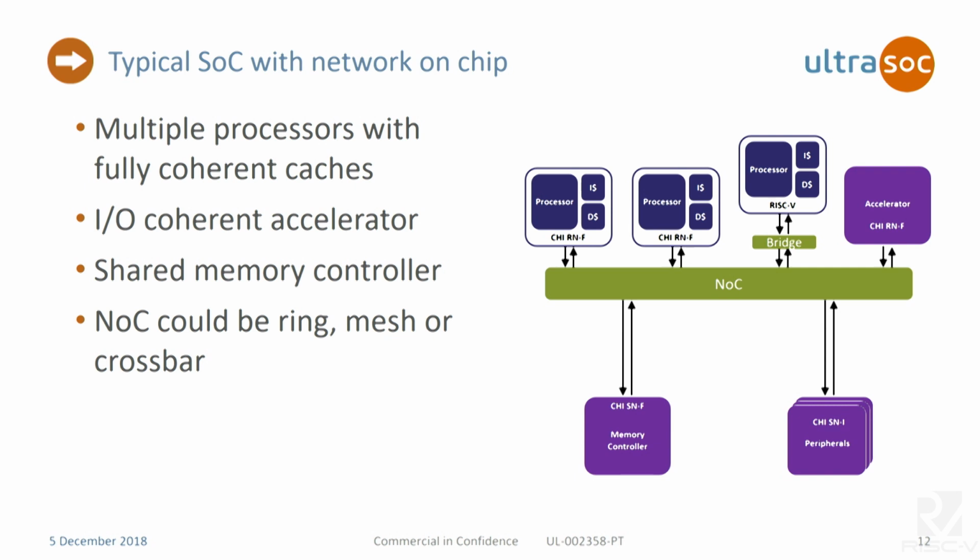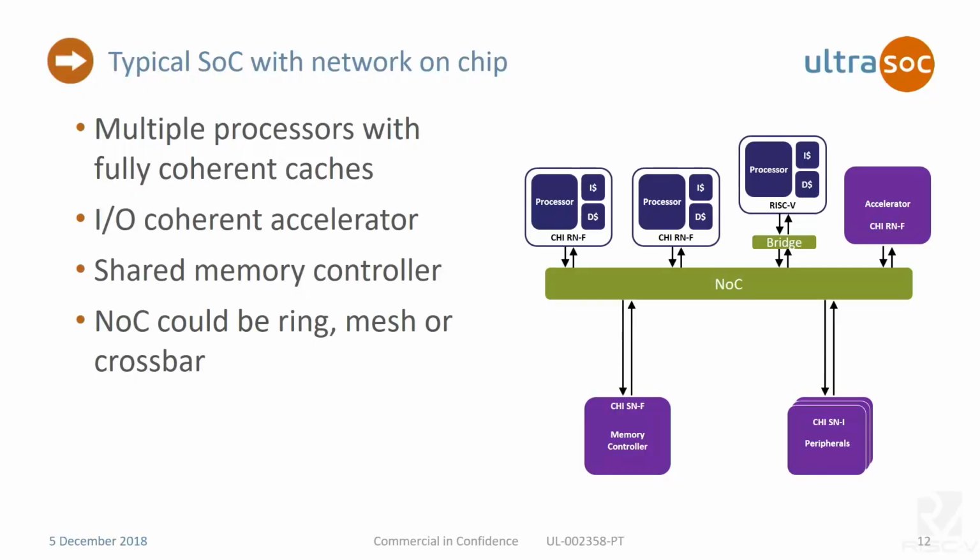So the cores that we have need to support the native interconnects. Yes, tiling's great, but we also need to be able to support existing NOCs out there. And I don't think ARM's going to change tiling anytime soon. CHI is a spec, so people implement it in different ways. You could have crossbars or rings. So whatever system you have needs to support that.